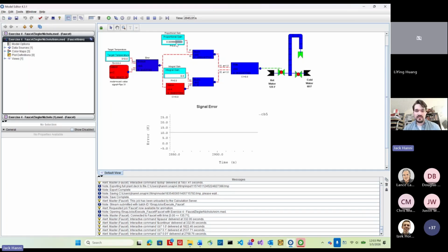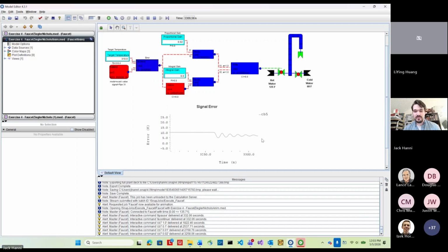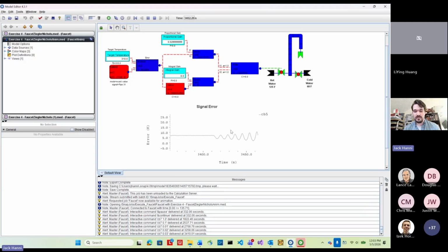And then you might start increasing so that you get one of the first values that it's unstable at. So instead of 1/100th, we might try 2/100ths. Stable again. 3/100ths. Now it's starting to get unstable. So then we can decrease it a bit.